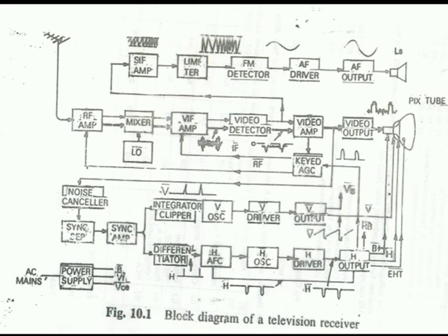That demodulation is performed by the video detector, and it gives back the Y signal and the color sideband along with the various synchronization pulses, because the Y signal and the different color signals were present at the input. We get all these signals after the demodulation process.